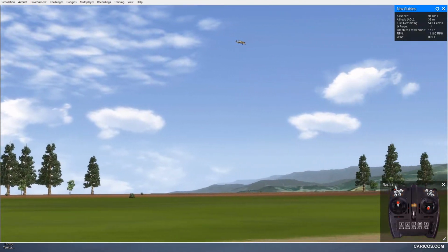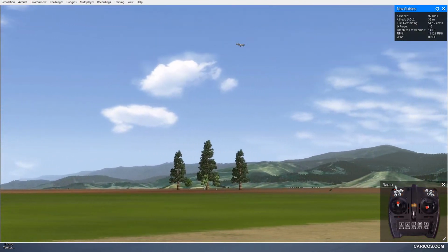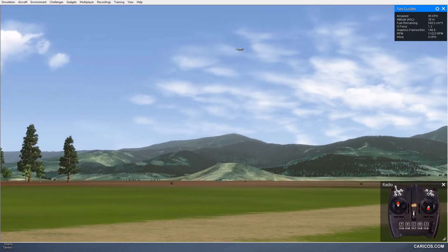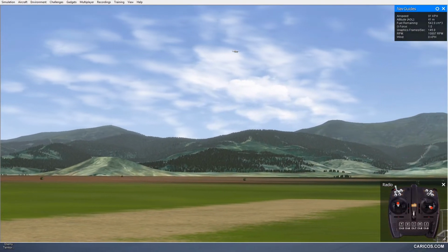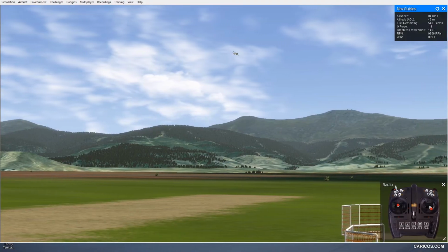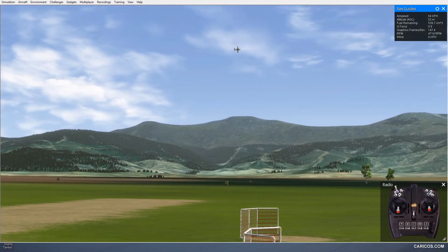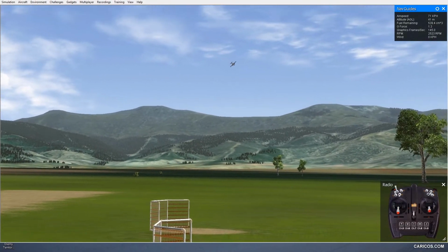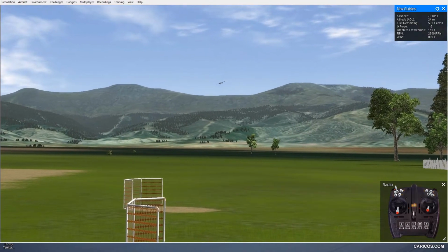As I'm entering the downwind leg, I'm trying to get the perfect amount of distance between the plane and the runway when I turn base. So I'm gonna turn base and then right into final and apply all my flaps. So we got full landing flaps and I'm down to idle.